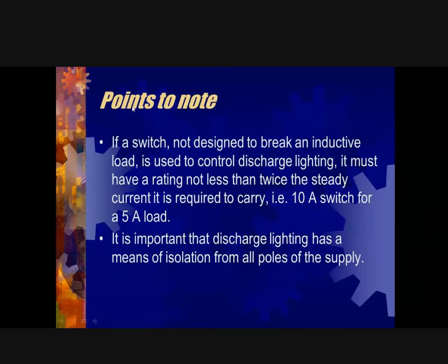All right, points to note when we're using discharge lighting: the switch must be designed to break an inductive load, meaning that if your load is, for instance, in this case, 5 amp, then your switch should be able to break 10 amp, right? Twice that of your maximum loading capability.